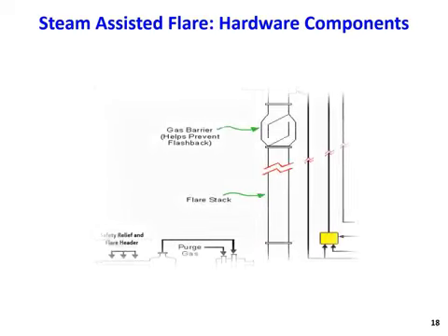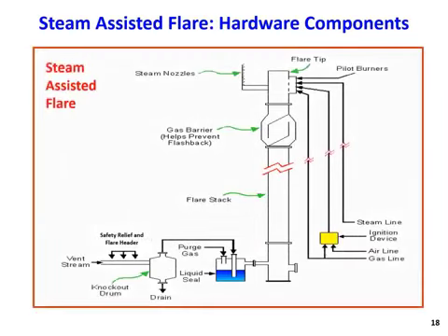It has such a configuration, with all those components that you have already seen. We have our heater, the knockout drum, then it goes through a liquid seal. The liquid seal can be inside the flare or outside, as you can see here, to remove some liquid condensates.